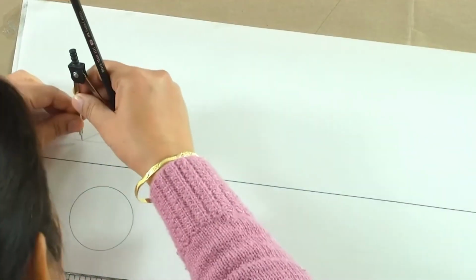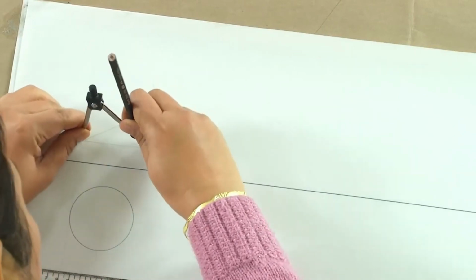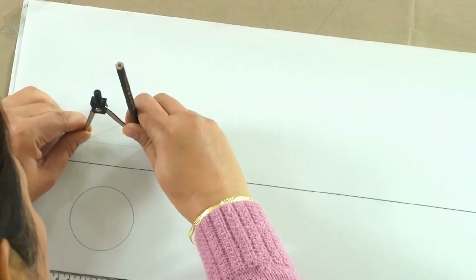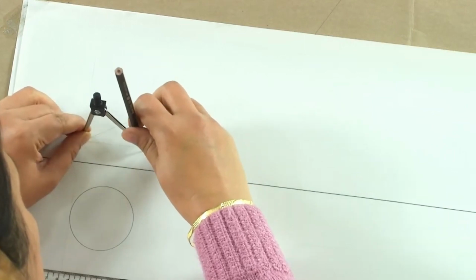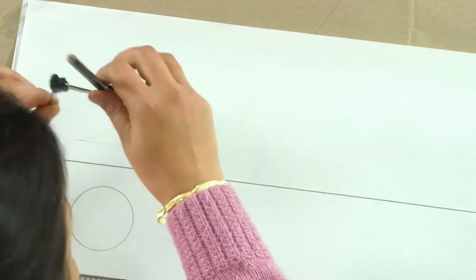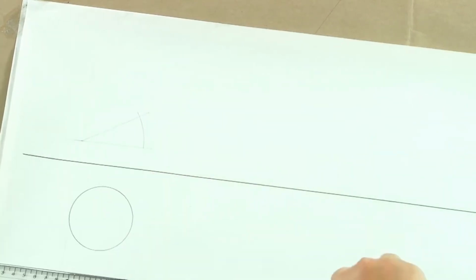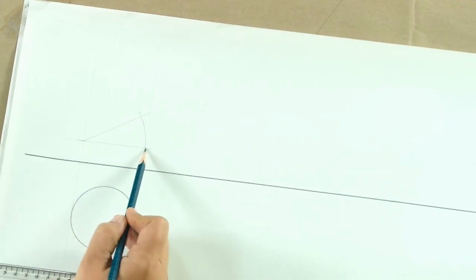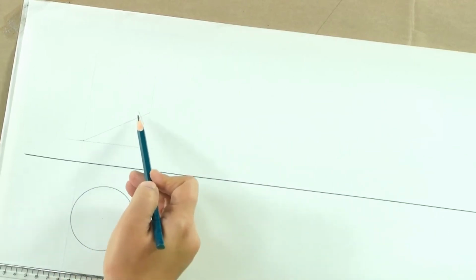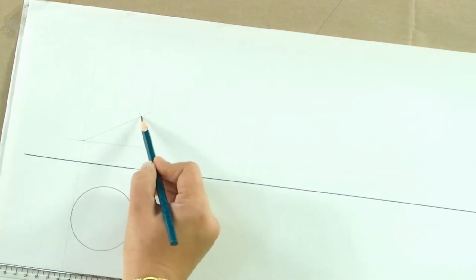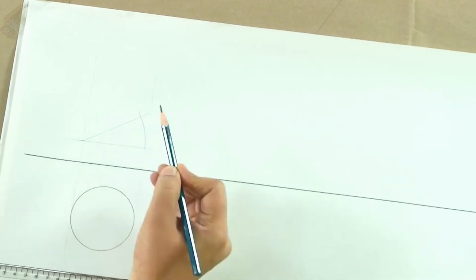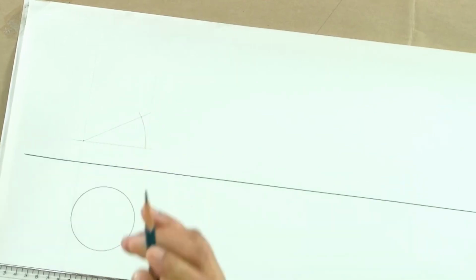So what will we have? We will have the same circle inclined at 30 degrees, and this is what we will have. So what we do is, we make the circle its true shape parallel to HP first and perpendicular to VP, and then we incline it by 30 degrees, which is the final trace of this circle.